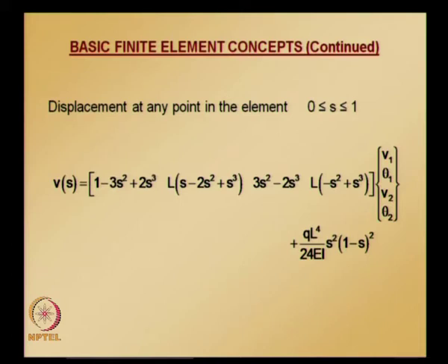The second term comes from the fixed end solution, which corresponds to the problem of a uniformly distributed load over the span. So this is the correction term, and you will not have this term if it is a point load problem, because you don't need to apply this correction term. This formula comes from the superposition method.